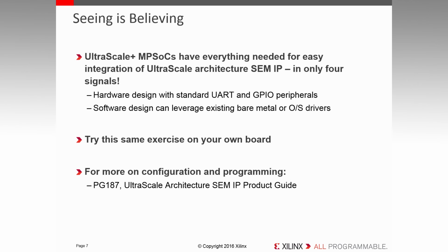Now you've seen the integration of the SEU solution is easy. The processing system peripherals are standard, built-in UART and GPIO, and you can leverage existing bare metal or OS drivers to access those peripherals. I hope what we just looked at makes you want to try it. This design was for the ZCU102, but the approach applies to any board with an UltraScale Plus MPSoC. The concept can also be applied to Zynq 7000 SoCs and even Xilinx FPGAs with MicroBlaze soft processors. Thanks for spending your time with me.